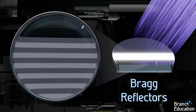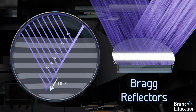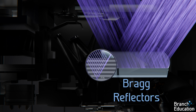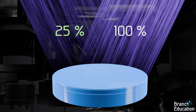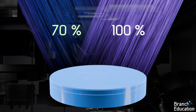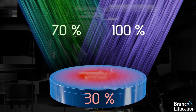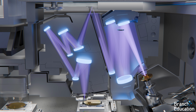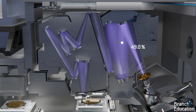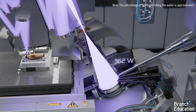When EUV light hits the surface of this Bragg reflector, only 3% is reflected at each boundary layer, while the rest passes through. But with so many layers, the cumulative 3% reflections add together using constructive interference, resulting in a total of 70% being reflected for a single mirror, while 30% of the light is lost and absorbed. However, with more than 10 mirrors in the optical system and only 70% reflection at each one, the final light hitting the wafer is less than 10% the brightness of the light emitted by the tin plasma, which is why the initial light from the source vessel needs to be as bright as possible.